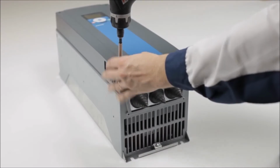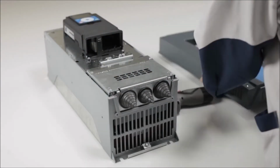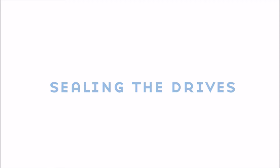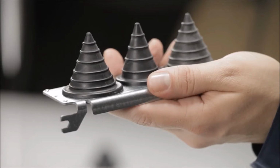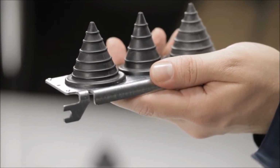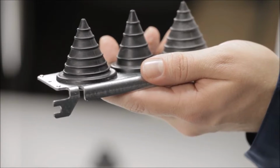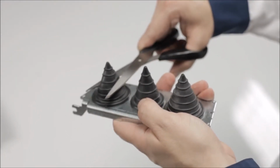Loosen the screws in each corner and remove both the VACON 100's main cover and its power terminal cover. Now you may have noticed a set of cable grommets down here on the table. VACON 100 comes with these to ensure that the drive is fully sealed and receives maximum protection from external factors such as dust or moisture.